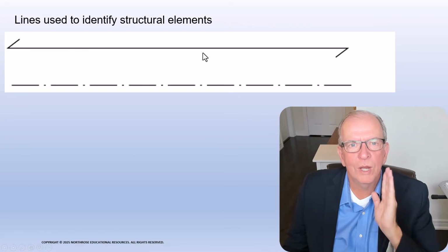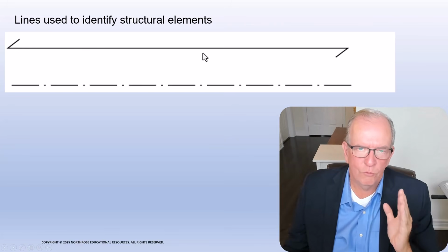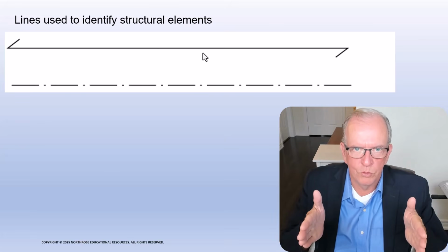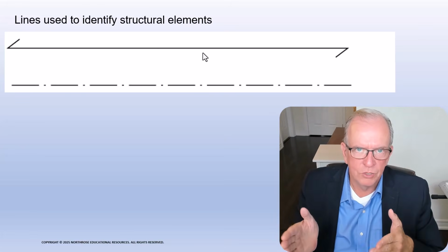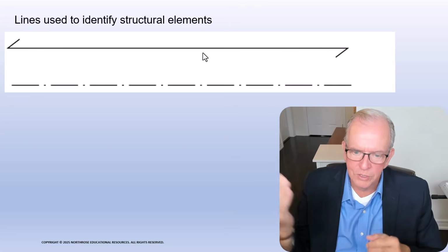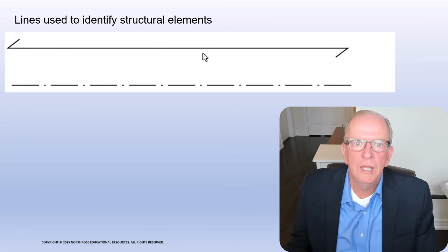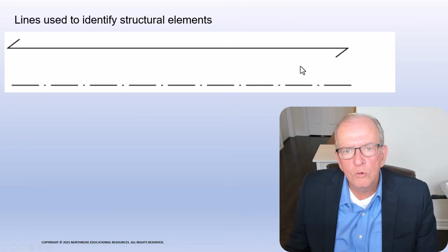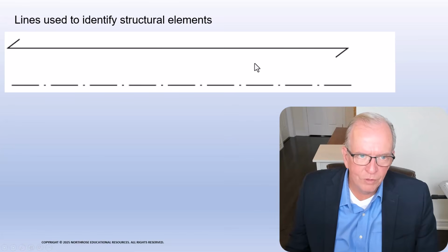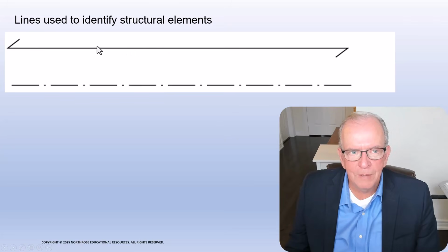This is the direction of the joists. Floor joists are what supports our floors in wood frame construction. The direction of the joist could be going this way, or this way. When you see this symbol, you know what direction it is, and you know it's for the floor joist. And then on top of it, they will say what it is. They might say 2 by 8 at 16 inches on center.